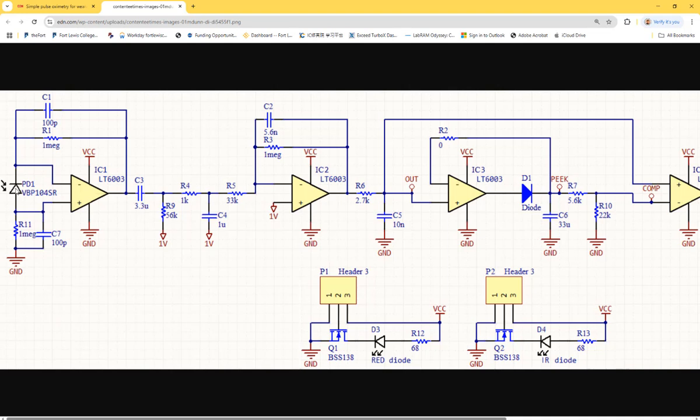So the first stage is performing as a TIA, the transimpedance amplifier, because it's converting the photocurrent into a voltage. Why? Because whenever this one generates a current, it pulls current this way. Ignore the caps first, okay? We're only looking at the DC part of it. So it pulls current that way to ground, from here to ground, right?